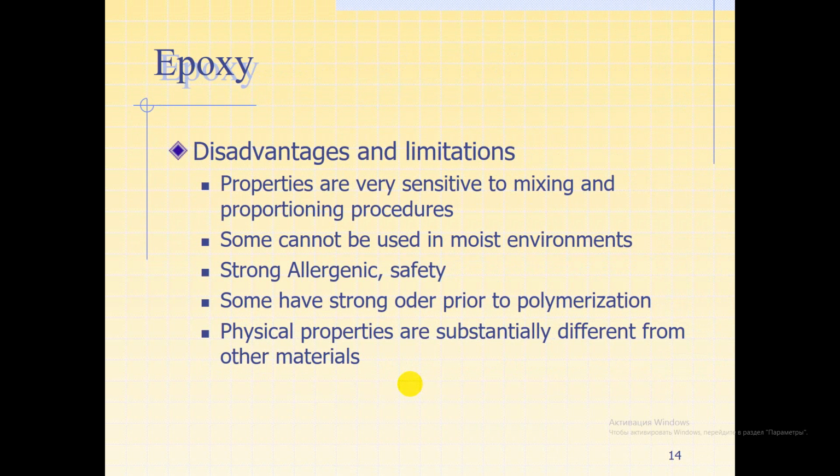Disadvantages and limitations of epoxy. Properties are very sensitive to mixing and proportioning procedures. Some cannot be used in moist environments. Strong allergenic and safety concerns. Some have strong odor prior to polymerization. Physical properties are substantially different from other materials.